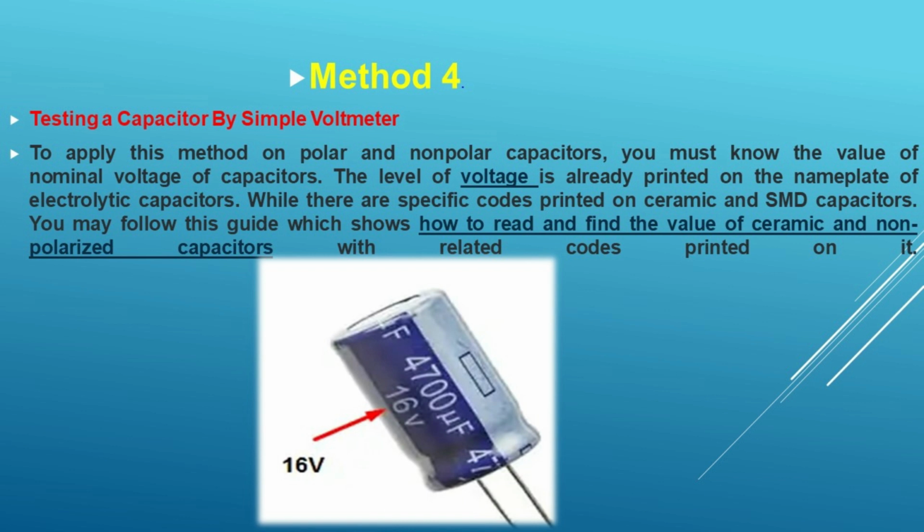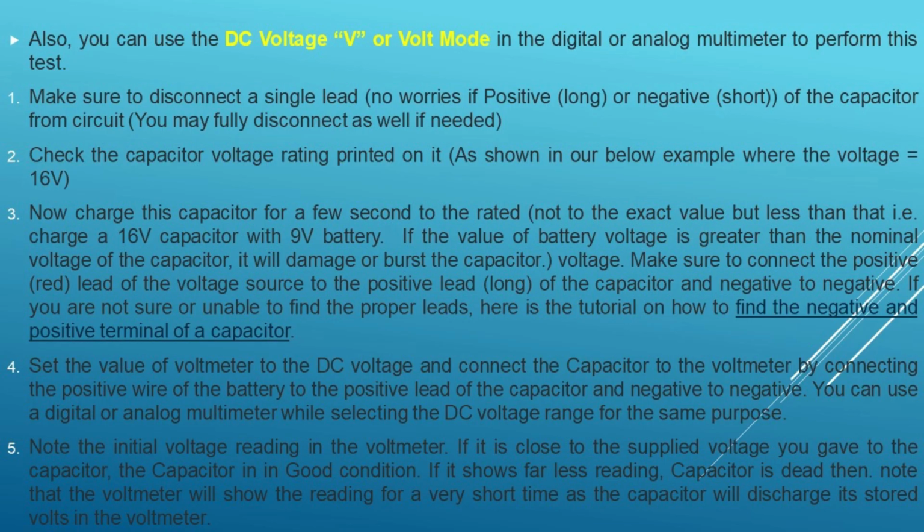Shorted capacitor will show very low resistance. Open capacitor will not show any movement, deflection, on the ohm meter scale. Good capacitor, initially, it will show low resistance, and then gradually increases toward infinite. It means that the capacitor is in good condition.